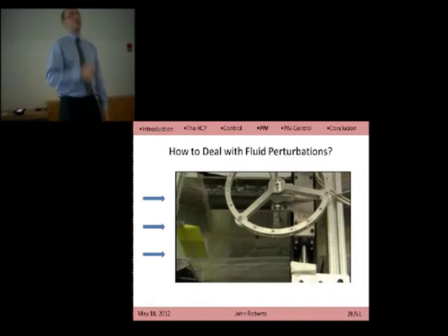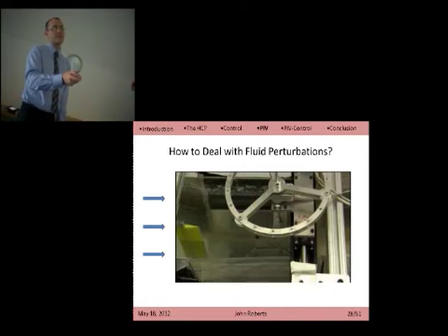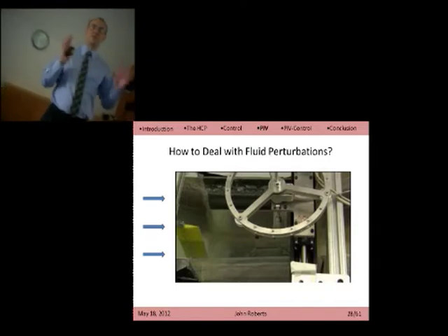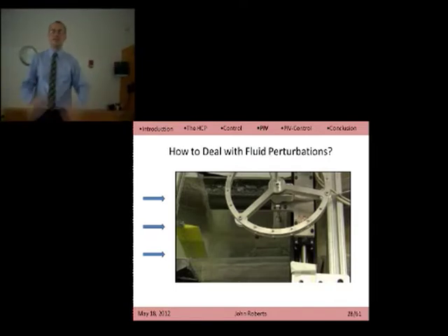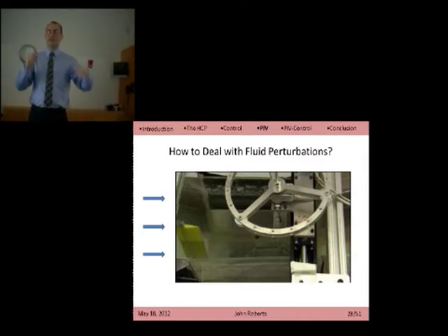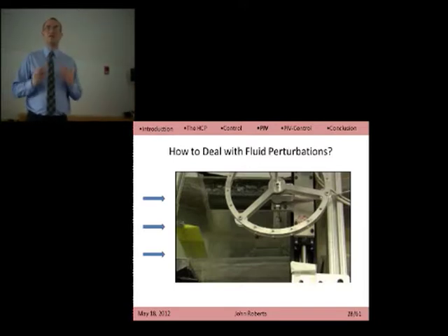So now let's say we actually have a perturbation to the system. So now you actually have to worry about this wing. And this wing is just called the perturbation wing. We can control it and kick it and send a vortex off downstream. So it'll advect downstream and hit the cart pole. We don't let the cart pole know what we've done though. So we can generate it to run these tests, but the cart pole is just getting hit as if it was unaware of the generation of that vortex. And it has to deal with that either as a perturbation, or later on we'll try to sense it and respond to it with foreknowledge of it coming.